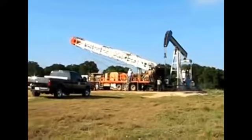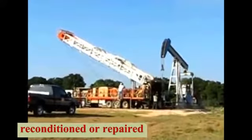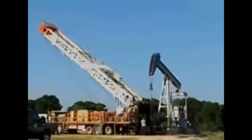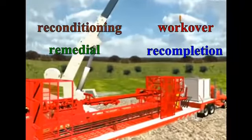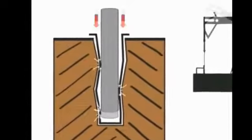Over time, therefore, a producing oil or gas well will have to be reconditioned or repaired if optimal production is to continue. Known as a workover, a recompletion, a reconditioning, or a remedial, the purpose of a workover is to re-enter the well to repair it.